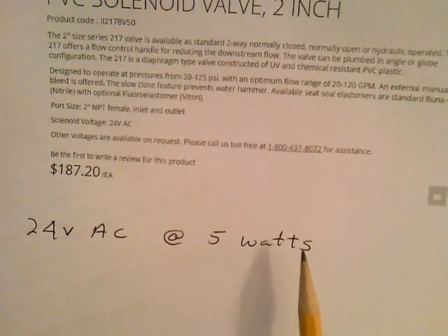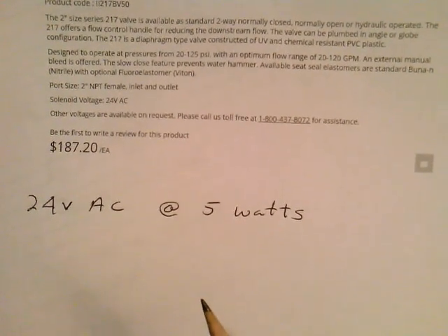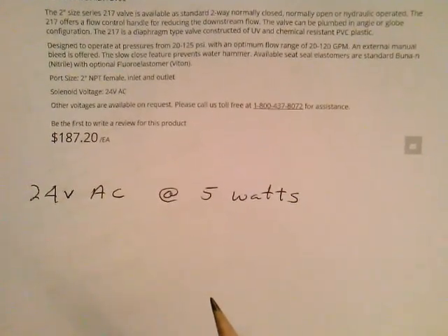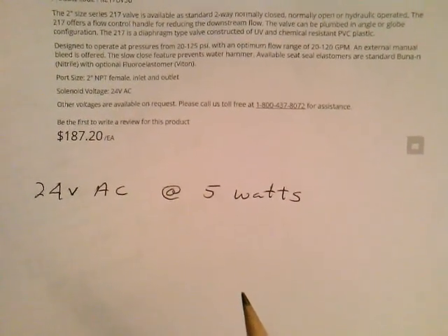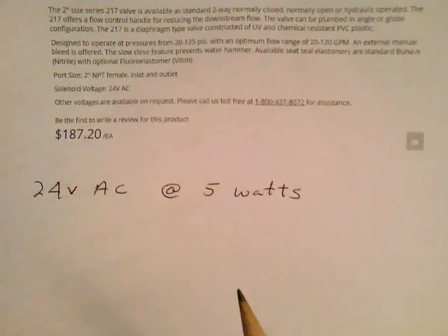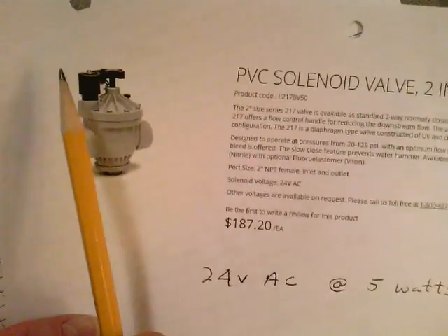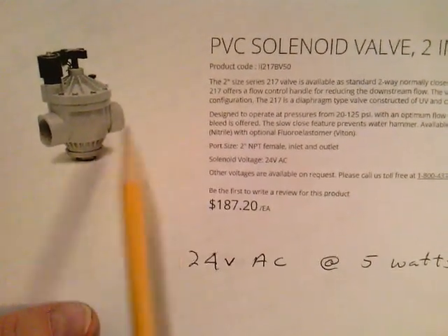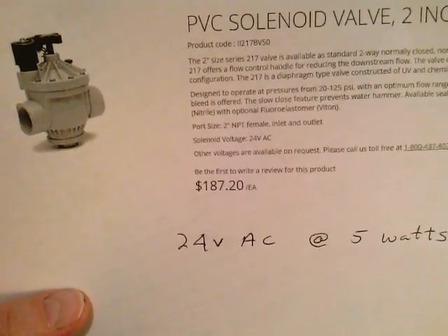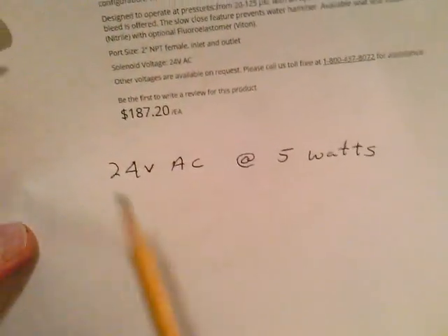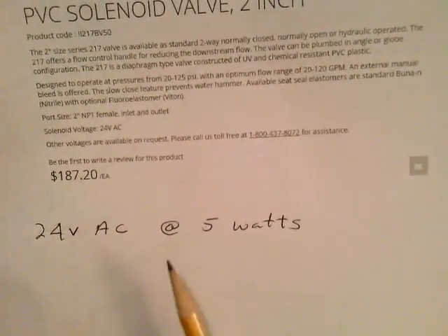Okay? So I wanted to find out if I could use a small little transformer that I bought. You've seen these little transformers, similar to the ones you plug into a router or a switch, that plug into the wall and have a little plug at the end. Well, I wanted to just cut that and resplice it right into the electrical wires on this valve to see if I can control this water flow. A lot of water flowing through there, 2-inch diameter. So the specifications on this solenoid valve were 24 volts AC at 5 watts.